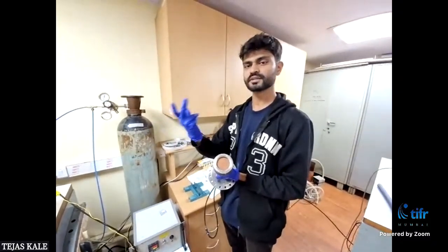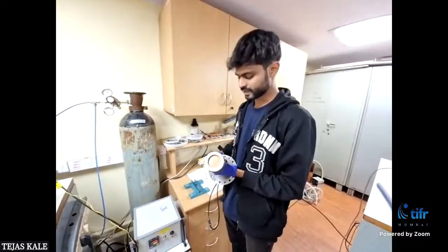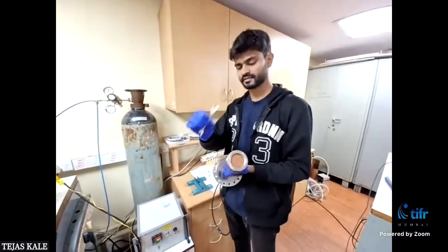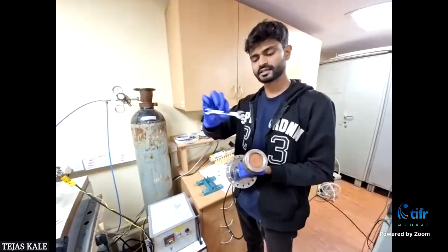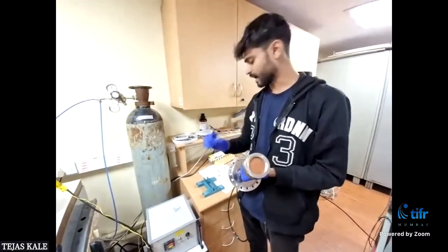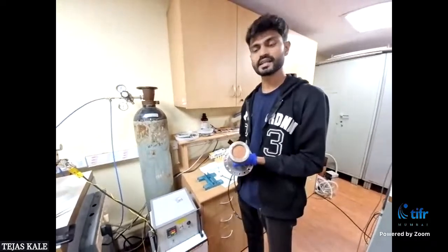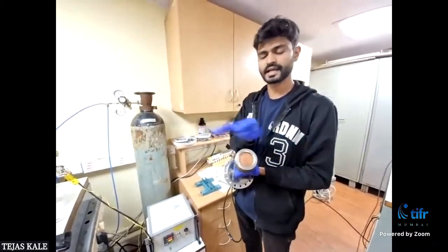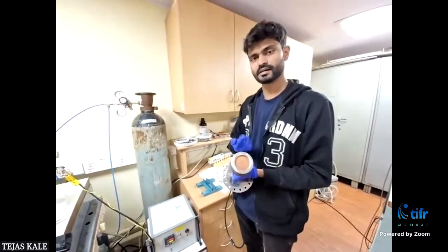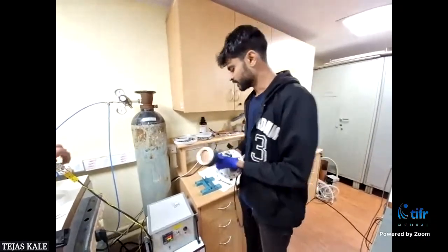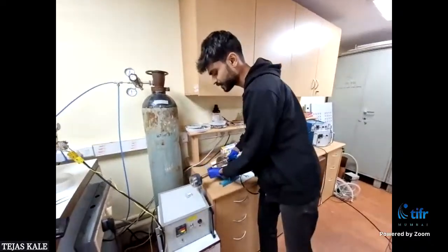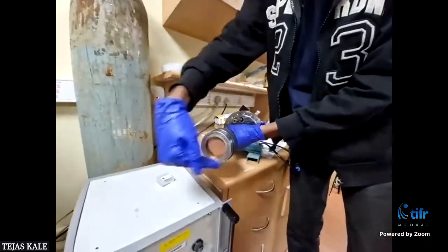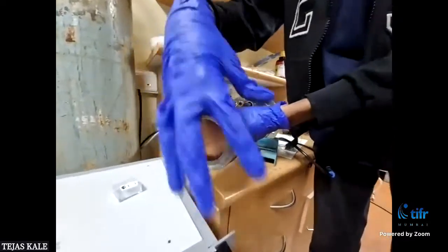The free electrons come from the sputtering gas, which is argon, and then there are magnets behind this copper target. So you can see it's sticking here. There are a lot of magnets behind. These magnets create a magnetic field which is perpendicular to this copper target. So the magnetic field will be on this side, and the electric field will be perpendicular to the magnetic field. This setup will create a trapping of electrons here, and these electrons start moving around in a circular or helical path around this target.